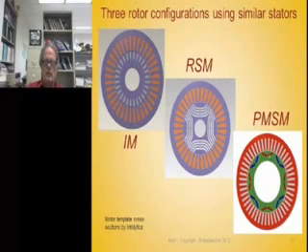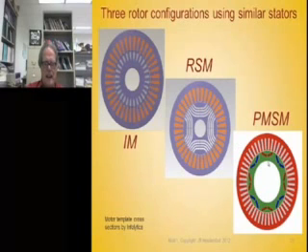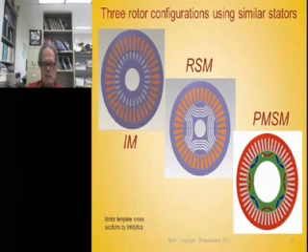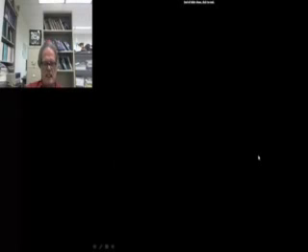This particular one is called an IPM, internal permanent magnet machine. This is a permanent magnet synchronous machine with an IPM rotor configuration. The magnets could have been on the surface up here, but they're inside, and they're shaped in a V, so we can spread them apart and get this soft iron in between, which gives this saliency. So those are the machines that we're going to study.